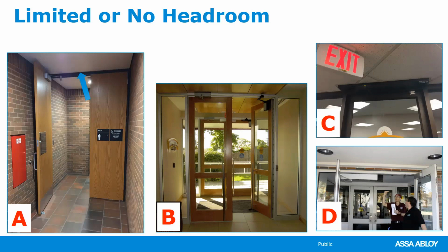The second thing we could do maybe would be to reduce the clear door opening as shown in picture D. So here the facility manager had no knowledge of a door mounted product, or maybe when this operator was installed, that product didn't exist yet. And so he reduced the opening size by mounting the operator in picture D. But clearly this is not something that we would suggest as a solution, and it may indeed be a code violation to place the operator there.